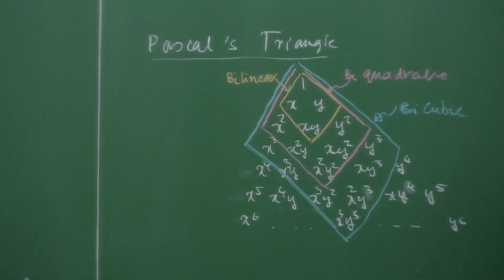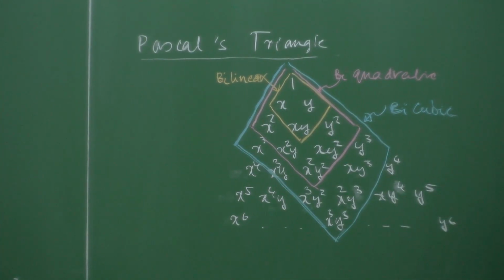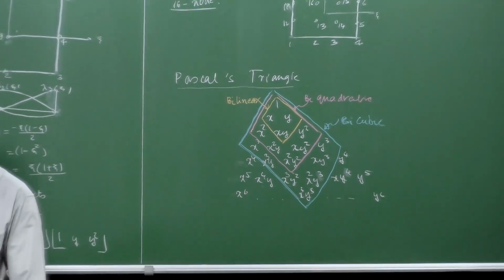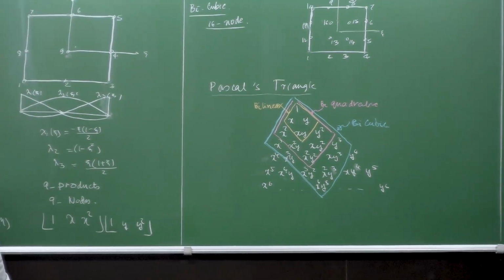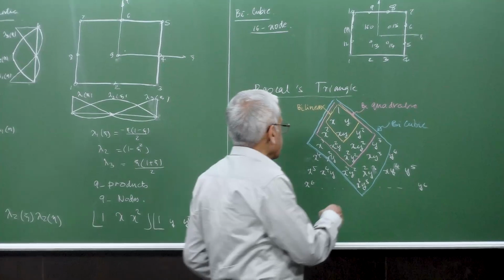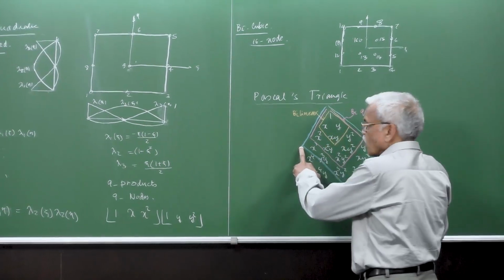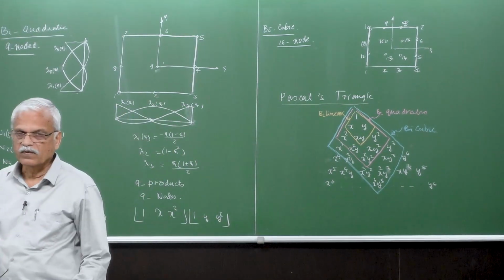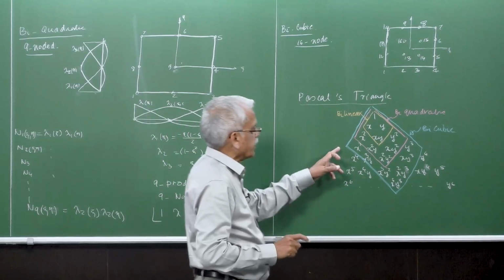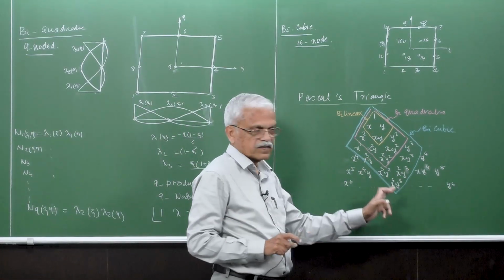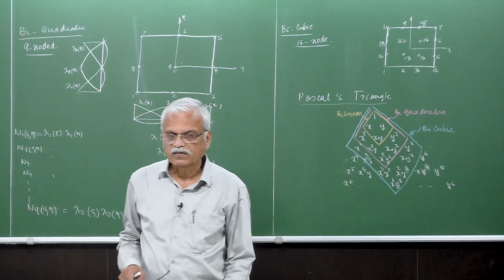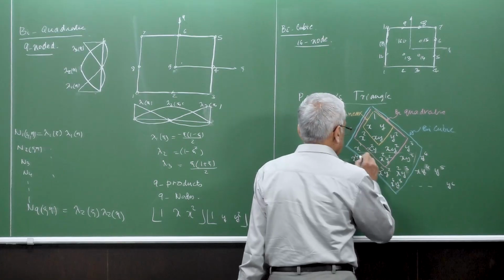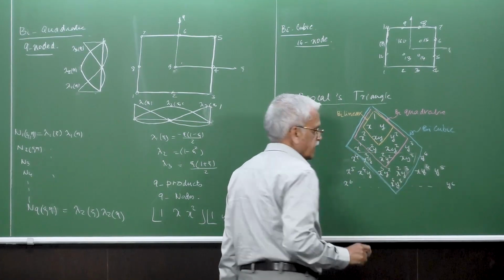So these higher order terms, which are incomplete polynomial degree of that row, will not help in the convergence rate. Like we said, h to the power of something, right? So here that is governed by the row which is complete. The convergence of the element is only governed by the row which is complete. So the higher order terms are there for the sake of construction of this Lagrangian element. So that's why it is possible to eliminate these things or anything higher order.